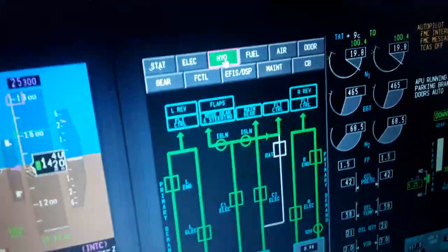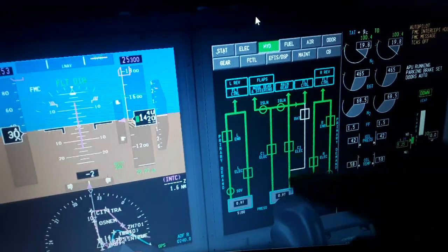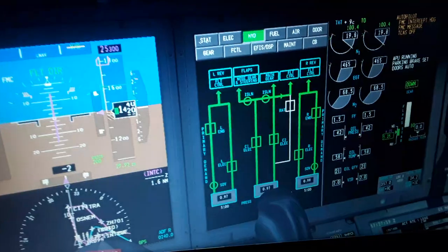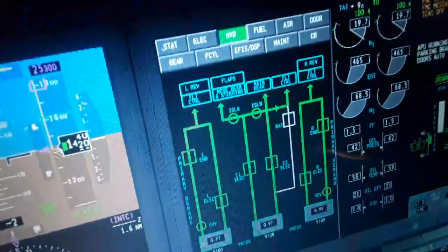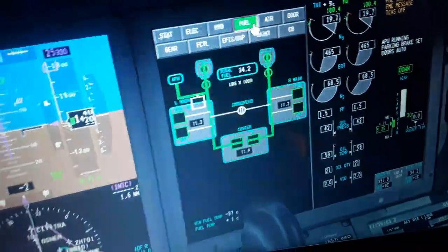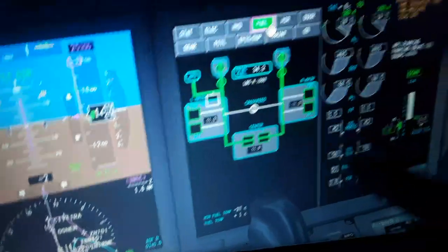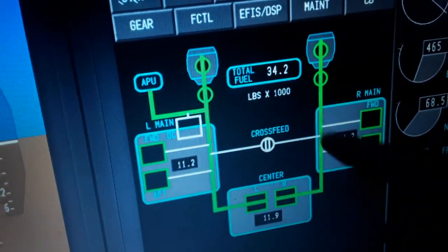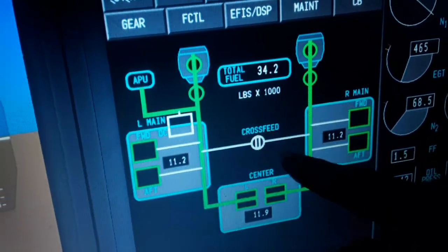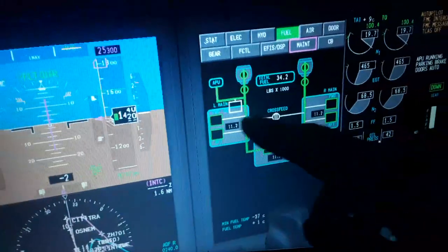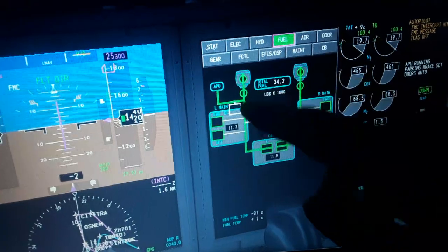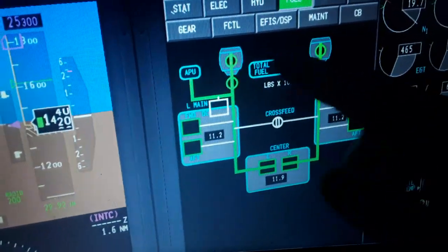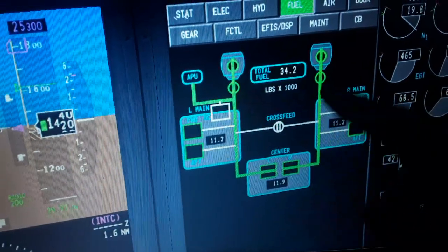Hydraulic systems here, left and right engine, electric C1 and C2, where the hydraulic fluid goes, and the pressure 5000 psi system, the quantity of hydraulic fluids. Fuel valves, left and right wing fuel tank, center tank, fuel booster pumps forward and aft. The crossfeed valve is off, but if we turn it on, you can feed either engine over here with either pump or either tank.